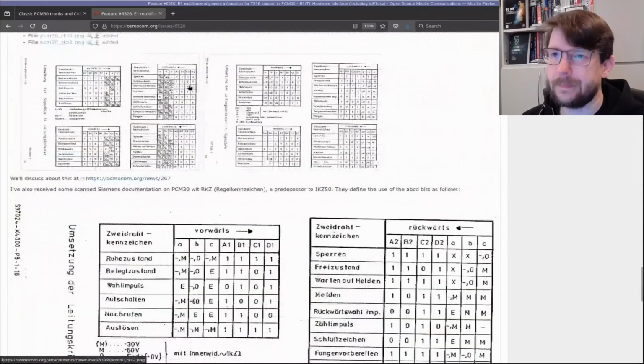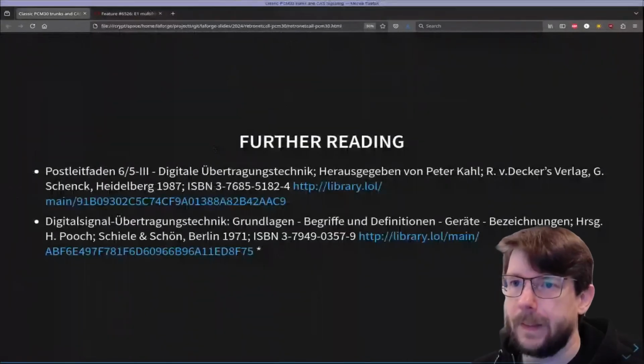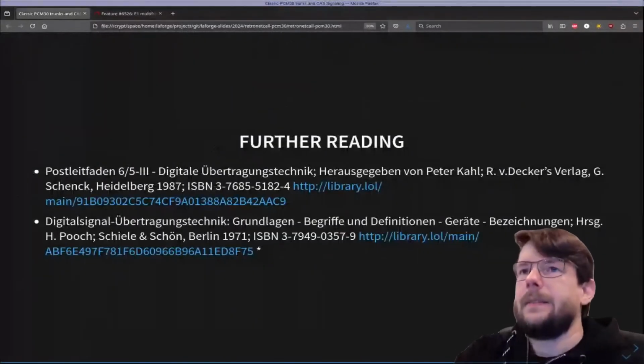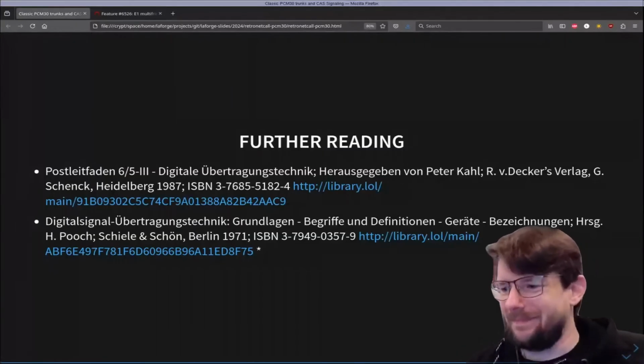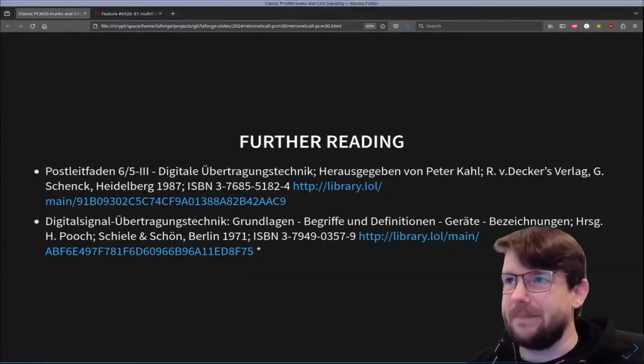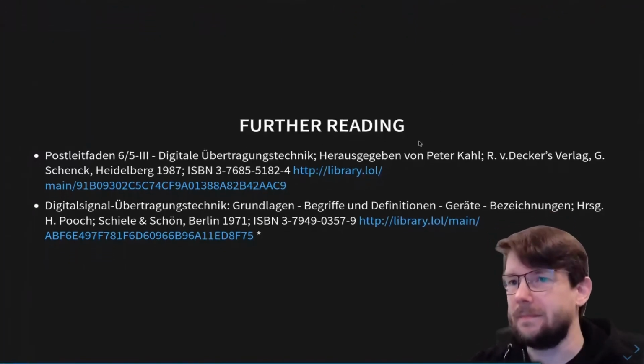But I also tried to read a little bit the firmware of the ICE1 USB. I had the impression that the multiframe number was already known internally. Yeah. So the firmware absolutely knows what multiframe is being transmitted, simply because the actual hardware that's implemented in the FPGA takes an entire multiframe as a block. So you don't submit frame by frame, you submit an entire multiframe. So the firmware absolutely knows the alignment.